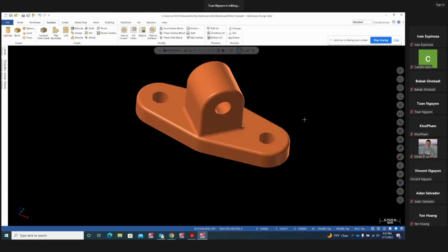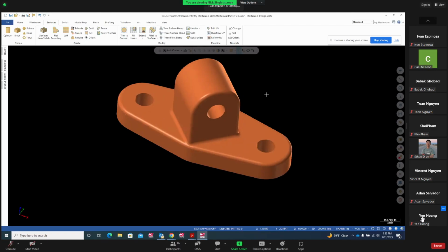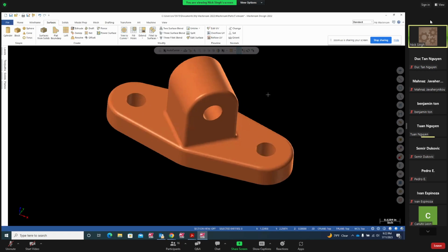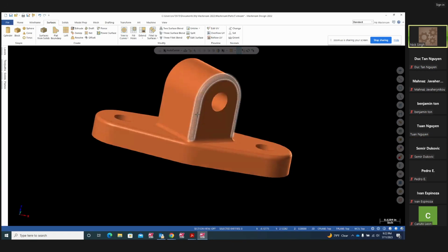I have questions. Yes. So when we're doing the fillet, the normal has to be always out, or no? Look at this fillet. We are cutting inside. In this one, the normal has to be in. This fillet is cutting outward. The normal has to be out. This is going to be all out, but this one is going to be in. Oh, I see. So it depends on the fillet.